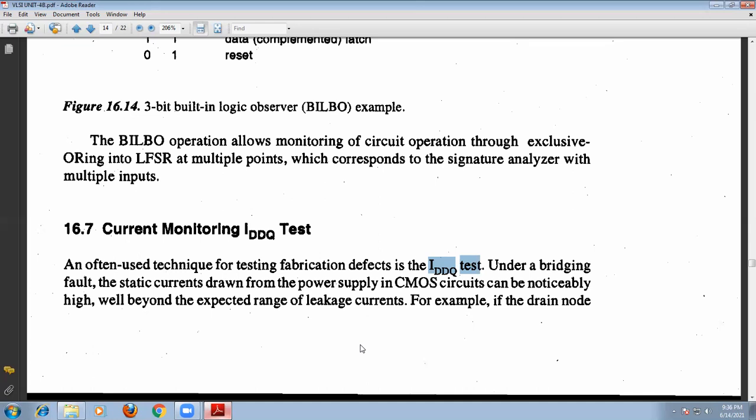Whenever the signals degrade, the output is not equal to VDD, but here we do not consider degraded output levels. You must have VOH, the output high state, equal to VDD, and the output low state always equal to 0. That means there is no degradation, so this type of IDDQ test will be possible.